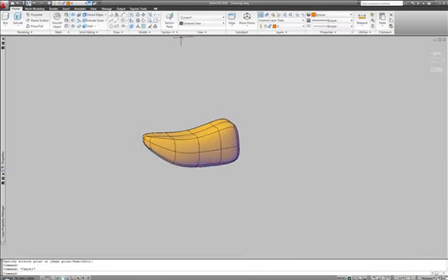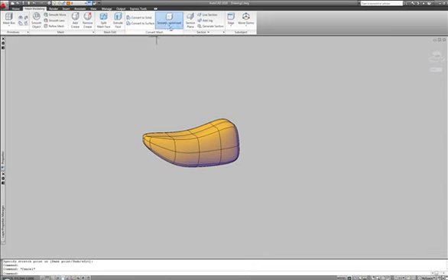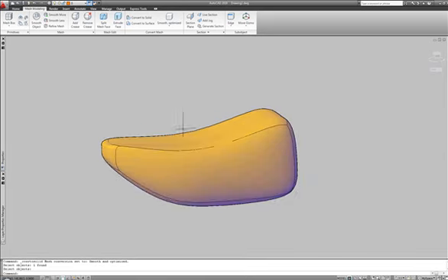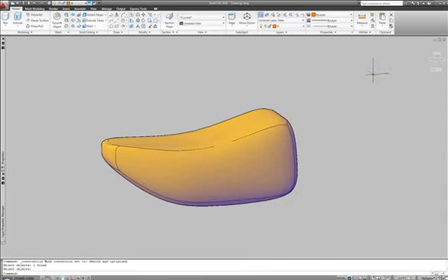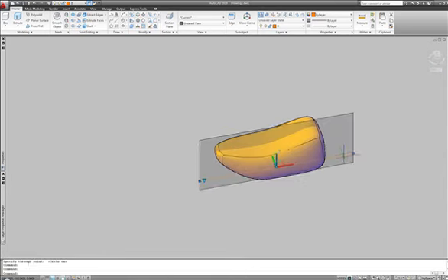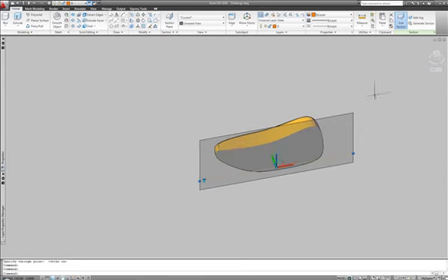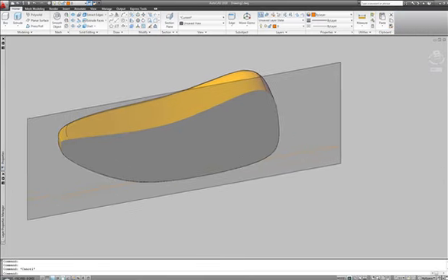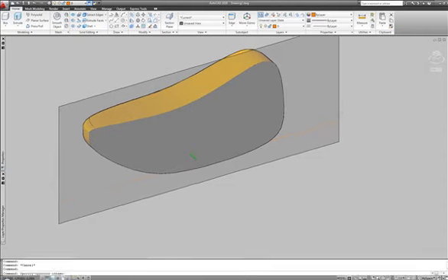Conversion from mesh into solids or surfaces is a unique capability within AutoCAD that creates either smooth or faceted solids or surfaces out of any watertight mesh. The optimization stitches faces with G2 continuity so the user can have the least amount of NURBS patches in the solid. This is also fundamental when exporting into Revit, for example.